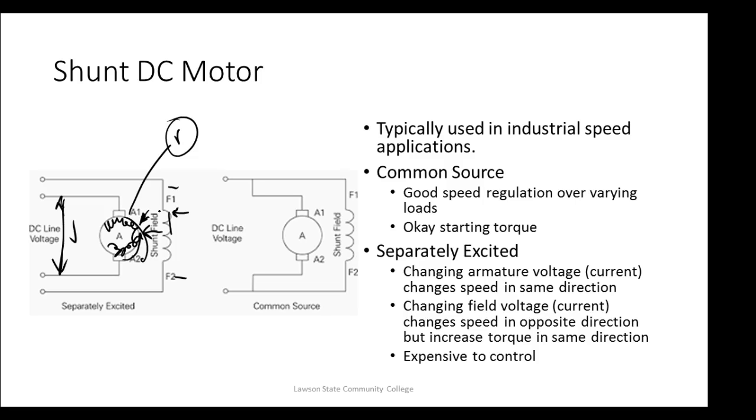So what's so strange about a DC motor is that the motor will run at a speed proportional to the applied voltage on the armature, and it's inversely proportional on the stator. Not the stator, guys, I said that wrong. On the stationary field. Do you refer to it as stator? No, I refer to it as the field and armature. But when they came out with AC motors, they started calling it the stator and the rotor. So over time a lot of people will refer to these as that, and it makes sense.